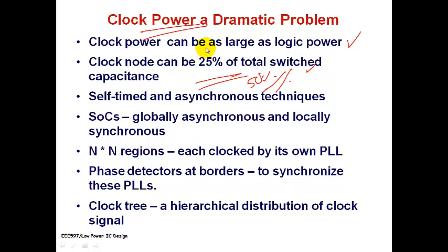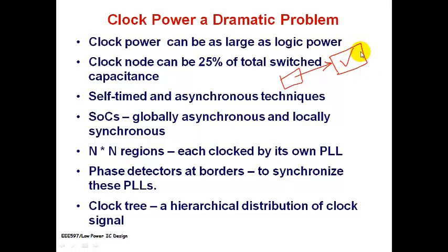If we don't want to have the clock dissipation, what can I do? I have one unit. The moment the data from this is ready, I could get my second one operating just by the use of the data identifying whether it is ready or not. That is using sort of handshaking signals, what we have discussed before.